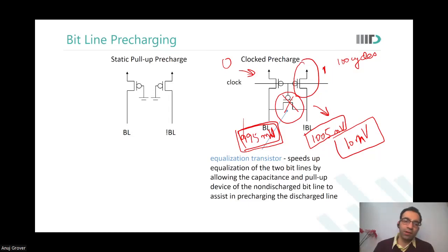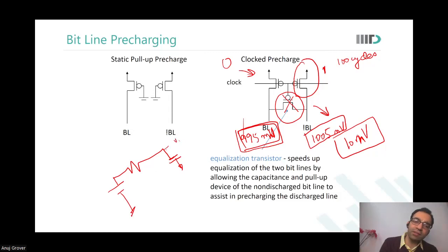Let us say any RC network. You connected a supply over here. Can you tell me when it will go to full VDD output? Sir, ideally it is infinite. It will never go to VDD. We know that 63% it will go in tau, an additional 20% it will go in 2 tau and so on. That much we know. But full VDD, can you tell? Ever? No, sir.